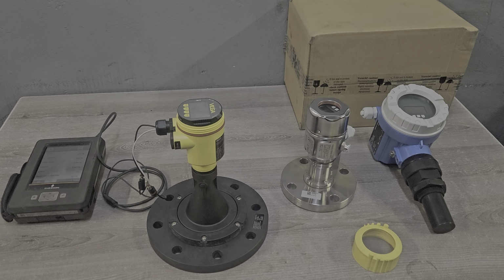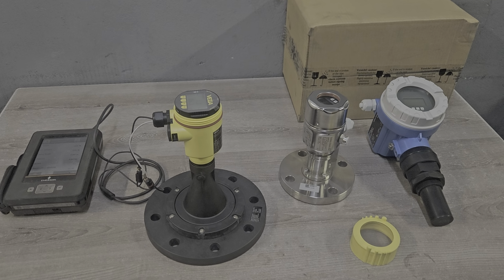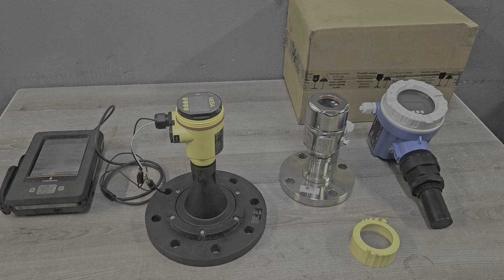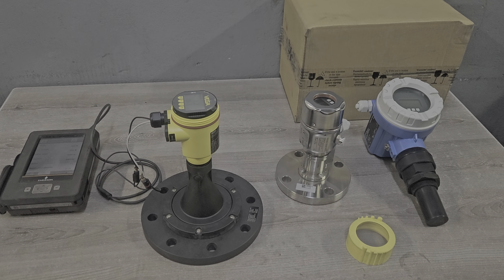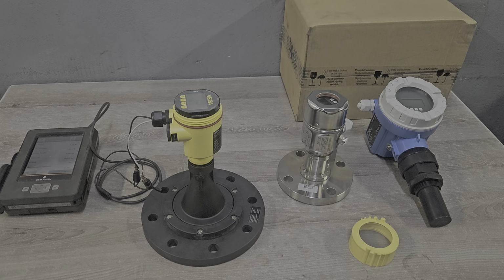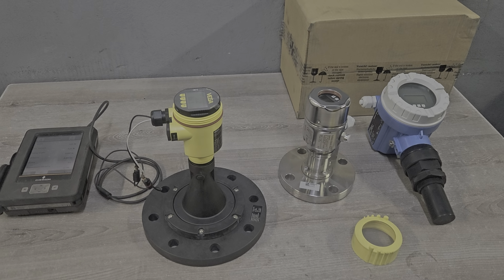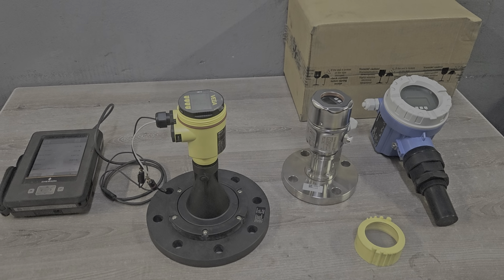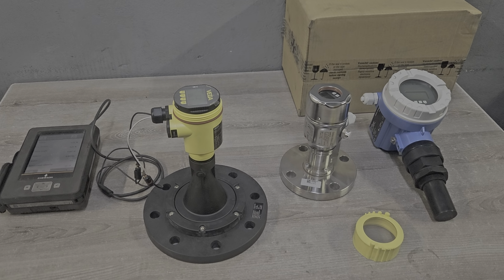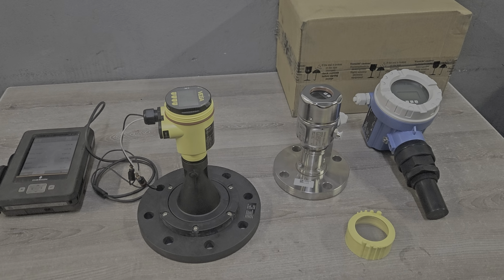So we can use a pressure transmitter to measure the level of a vessel in a way that the more water you put in a vessel, the more pressure is applied on that instrument. And then we can scale our instrument accordingly. Through the scaling, we will know that a certain pressure is equivalent to a specific level. But that will require us to take into consideration the density of the medium and also the height of the vessel, the dimensions of the vessel.